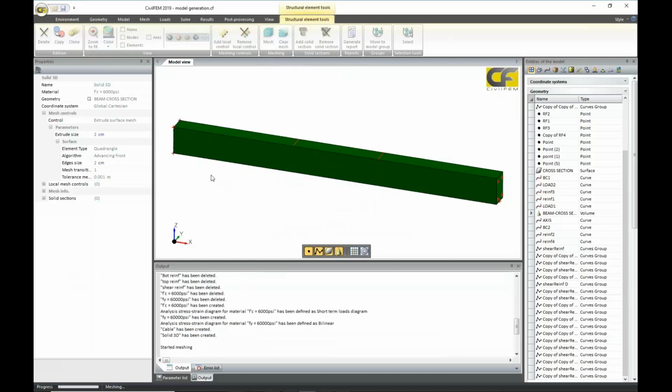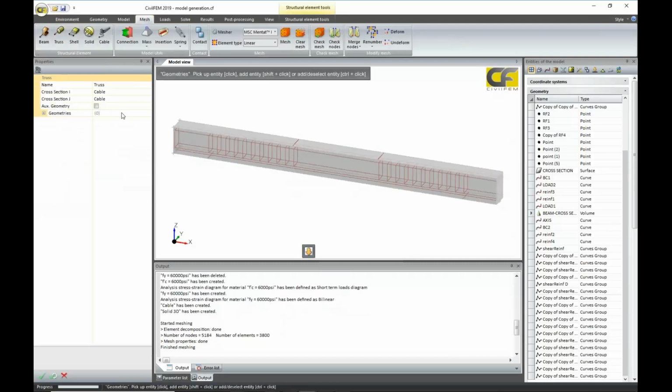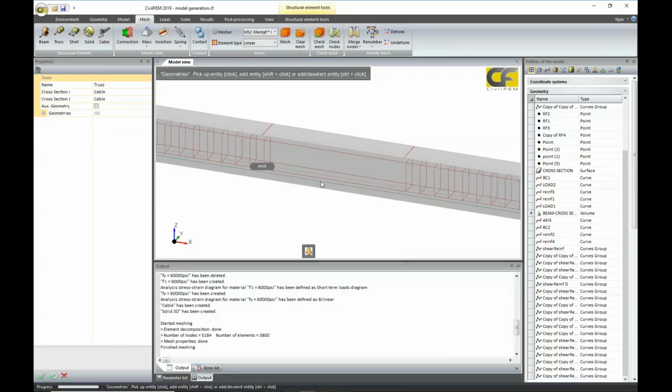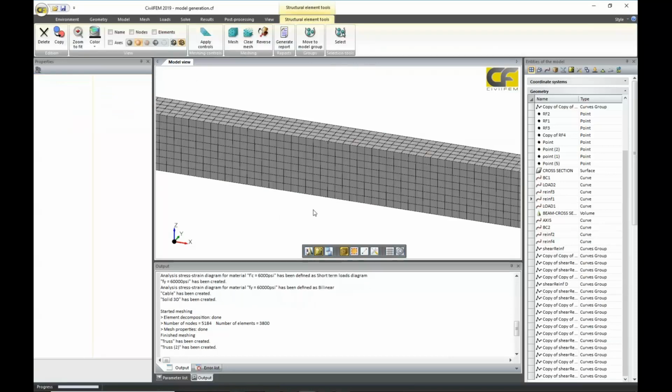I generate the mesh of this. Here you can see the meshing progress. The finer the mesh, the more accurate you have, but always, yes, you can perform an estimation. In the same way, I can generate the reinforcement. So well, I'm going to add this reinforcement for bottom reinforcement. For example, this one and this one, and just clicking here, I generate.